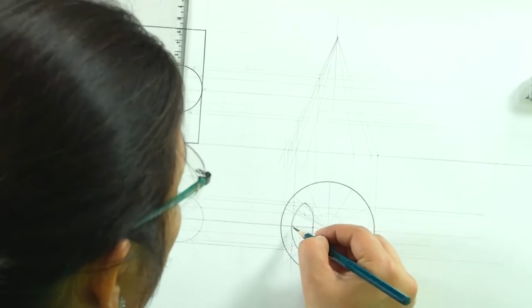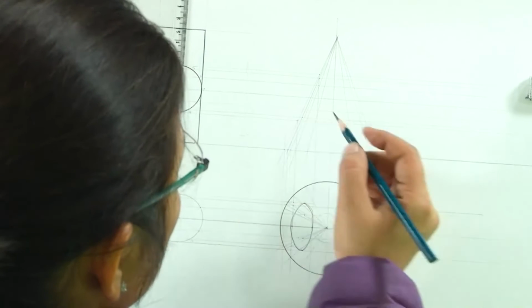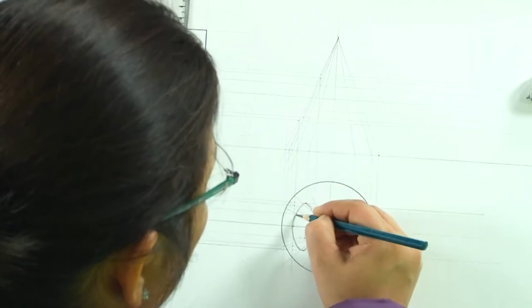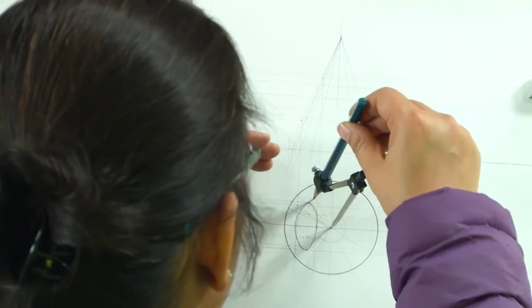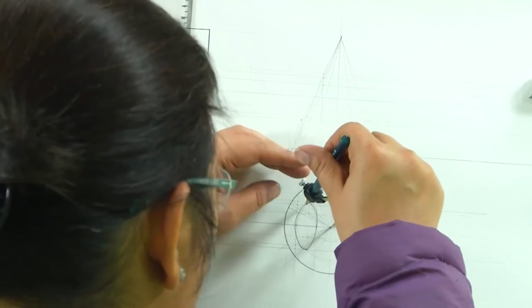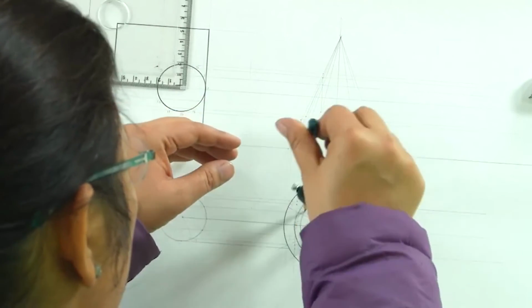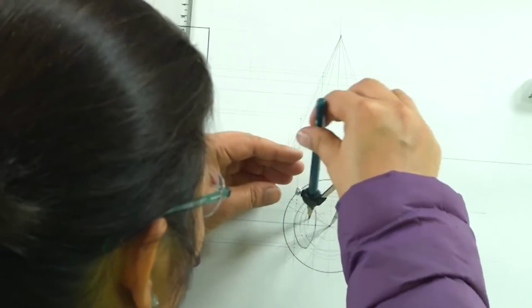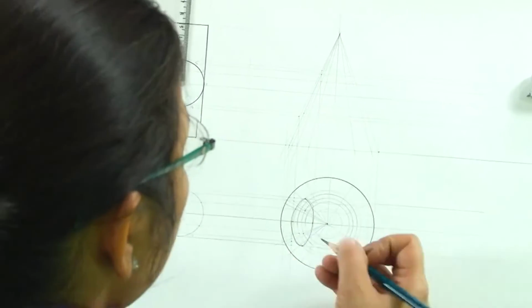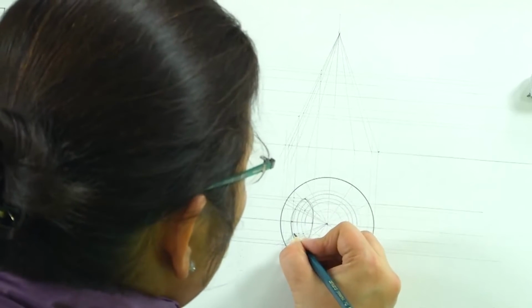So, this is where the bottom part of this circle is going to come. The second is where this bottom part of this circle is going to come. So, we will just be drawing the concentric circles through these generators, and wherever they intersect, through these generators in the top is where we are going to get each of these points in.